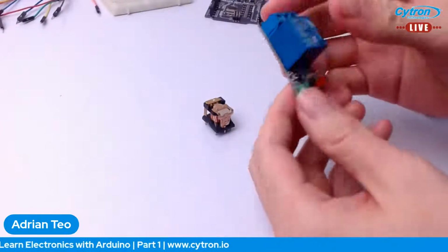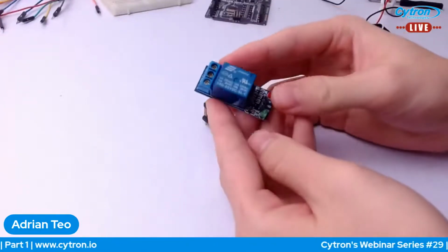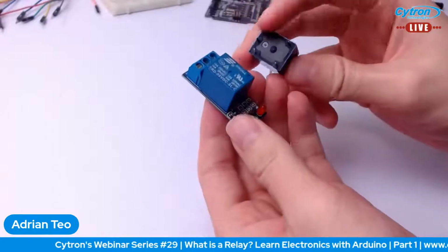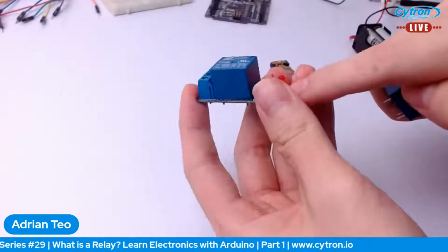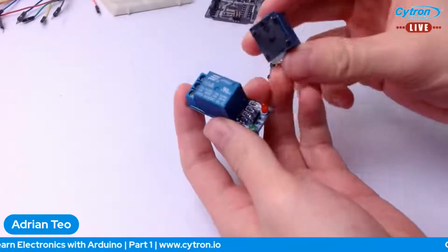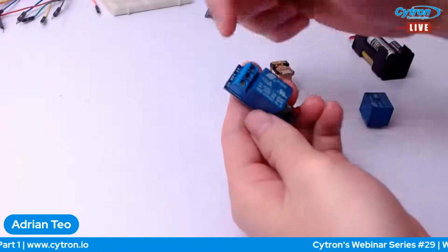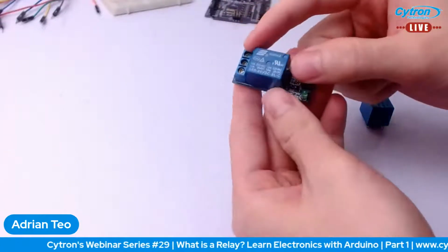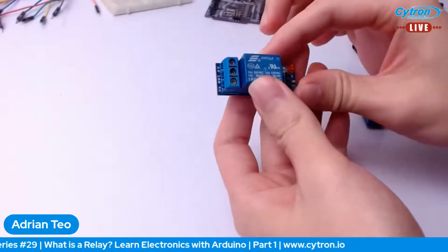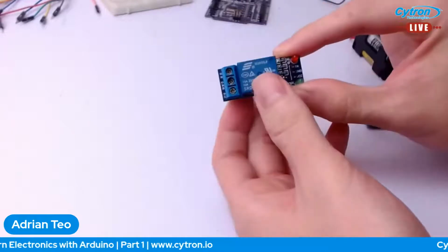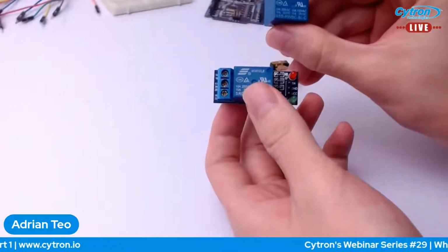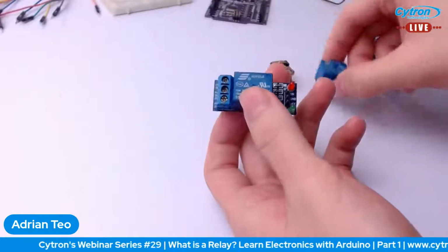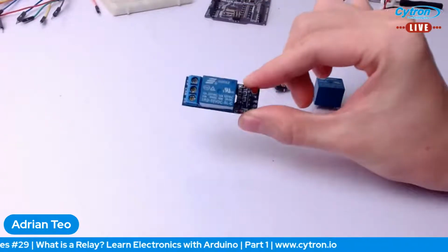So another relay that I would like to use is this relay. This is a very common single channel relay. It basically connects every pin down here into these ports and pins and LEDs for you. So you don't have to solder anything. You can just directly take your wire and connect it, screw it in, and then connect your wires, power on the relay, and then you can use it almost immediately. It makes it simple, and students can try using this kind instead of this. Even though this is so much cheaper, to use it, you need to solder it on a PCB and stuff, and it makes it troublesome. Okay, so this is what I'm going to use in a demo lab later.